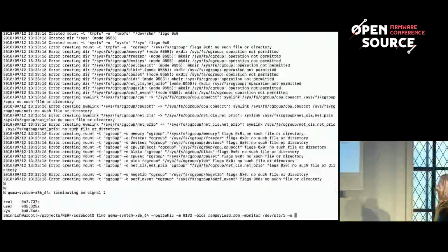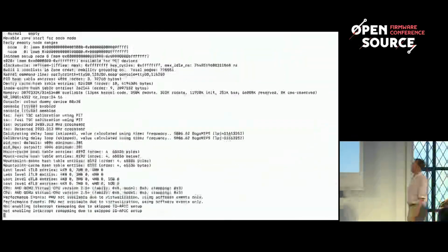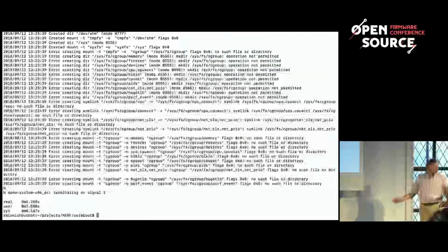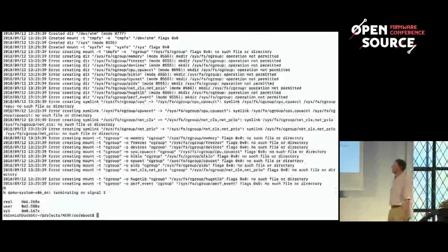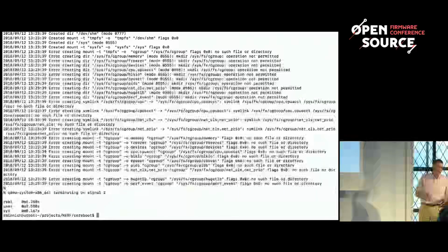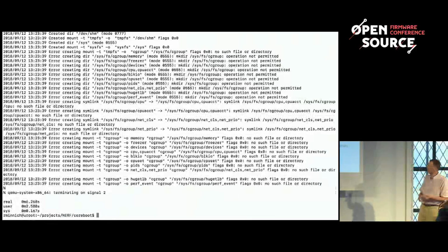And here's the RAM payload. Even in QEMU, you can see, same time, so I lied. Anyway, generally this seems to be faster, and it's not surprising. If you load the kernel from the ROM stage, it's hard to see it being much slower than loading the RAM stage from the ROM stage and then loading the kernel from the RAM stage.